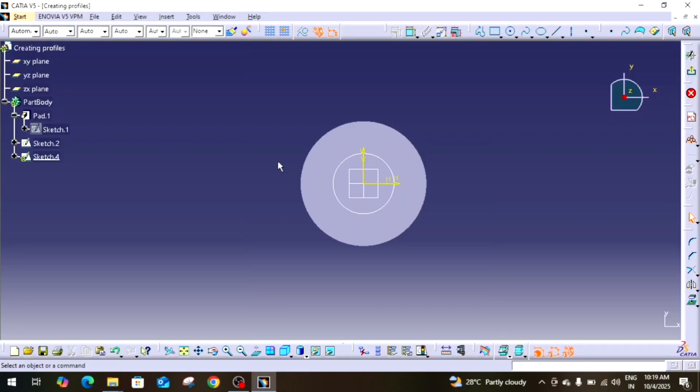Geometry creation. Sketch geometry is created using the tools available in the profile toolbar. Using this toolbar, we can create geometry. First one is the user defined profile. These are the predefined profiles. Here you can find the rectangle, oriented rectangle, parallelogram, elongated hole, cylindrical elongated hole, keyhole profile, hexagon, centered rectangle, centered parallelogram.